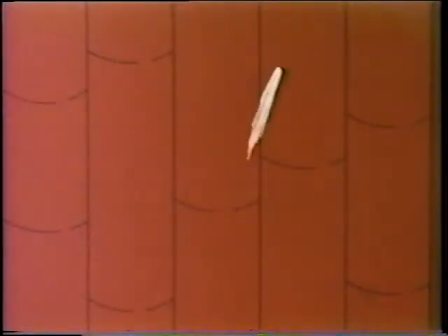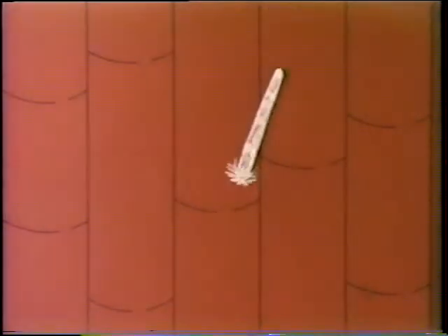Pinhole leaks allow steam or water to leave the tube in a concentrated stream. If this stream is directed against another tube, it will erode it, eventually producing a failure. This is called steam gouging. Steam gouging looks as though the metal has been blasted away and the resulting cavity polished. The cavity is extremely smooth and has an irregular shape.